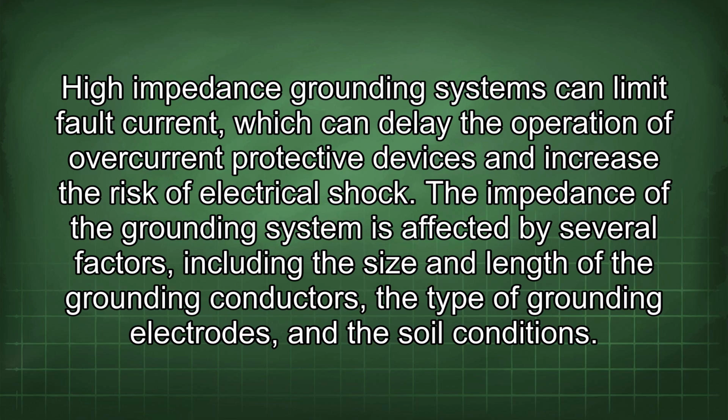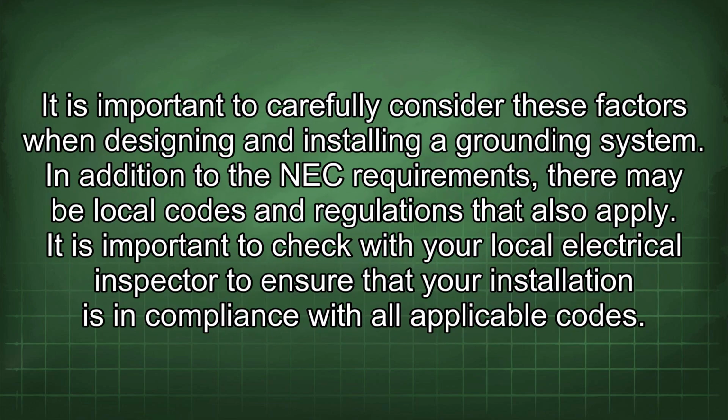The impedance of the grounding system is affected by several factors, including the size and length of the grounding conductors, the type of grounding electrodes, and the soil conditions. It is important to carefully consider these factors when designing and installing a grounding system.